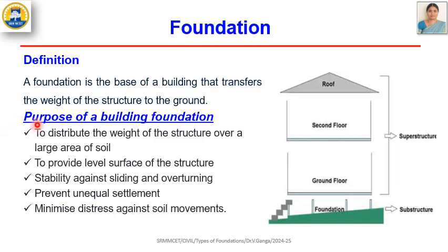Now, the purpose of the foundation. The building foundation serves many purposes. It distributes the weight of the structure over a large area of the soil. It provides or maintains the leveling of the structure, or level surface of the structure. It prevents sliding and overturning, and it also maintains the stability of the structure. It prevents unequal settlement, and it minimizes the distress against the soil movements.